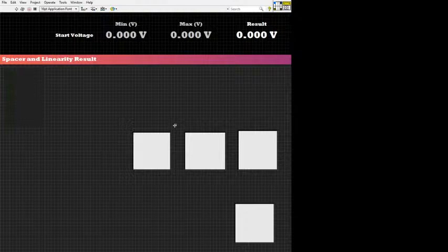I'll create a test VI. I'll put a subpanel on this test VI, and I'll just launch the actor inside of the panel so I could do debugging this way if I want to break things down a little easier rather than have it inside the entire application. And that's been my approach towards testing out these user interfaces one at a time without having the whole application completely developed.